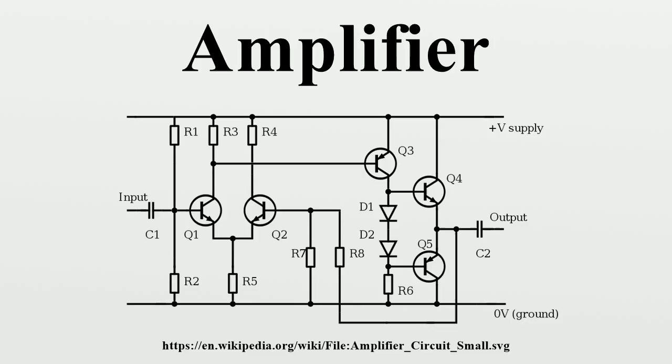Figures of merit. Amplifier quality is characterized by a list of specifications that include gain, the ratio between the magnitude of output and input signals; bandwidth, the width of the useful frequency range; efficiency, the ratio between the power of the output and total power consumption; linearity, the degree of proportionality between input and output; noise, a measure of undesired noise mixed into the output; output dynamic range, the ratio of the largest and the smallest useful output levels; slew rate, the maximum rate of change of the output; rise time, settling time, ringing and overshoot that characterize the step response; stability, the ability to avoid self-oscillation.